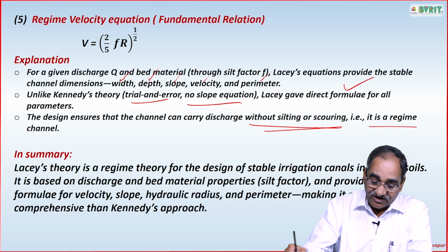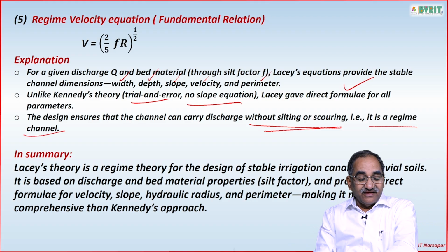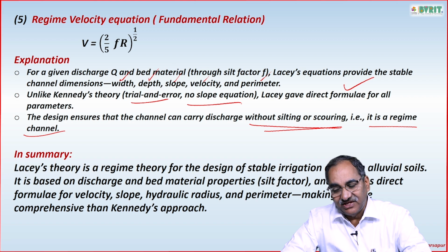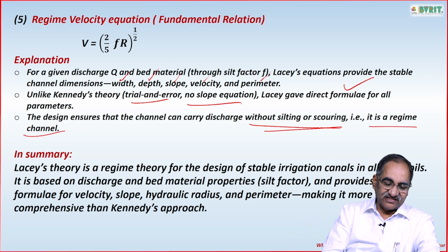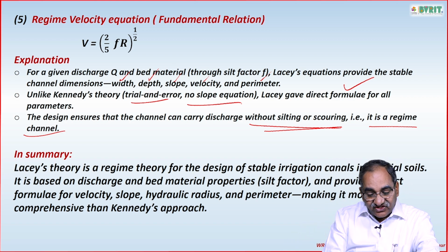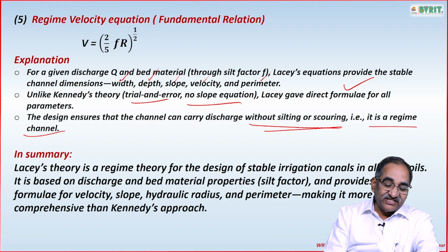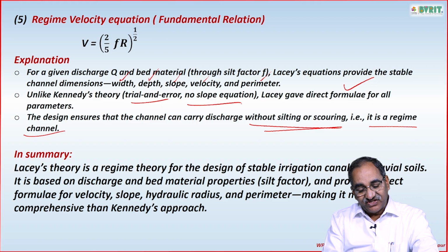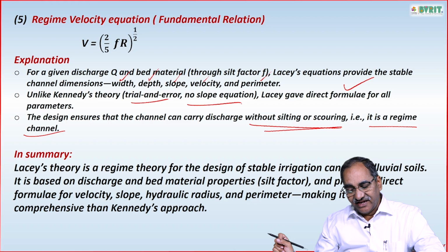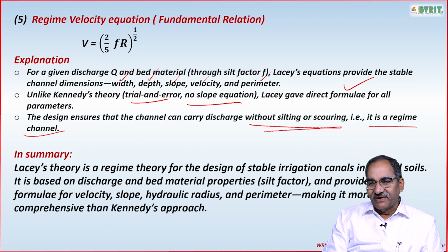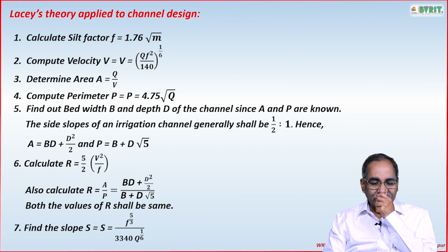So it is a regime channel. In summary, Lacey's theory is a regime theory for the design of stable irrigation channels in alluvial soils. It is based on the discharge and bed material properties and provides direct formulae for velocity, slope, hydraulic radius and perimeter, making it more comprehensive compared to Kennedy's theory.